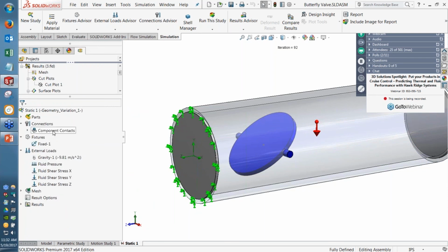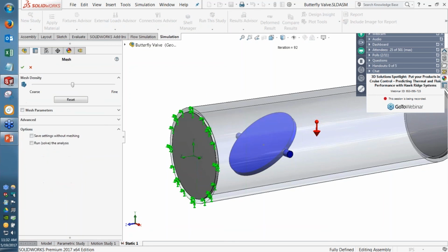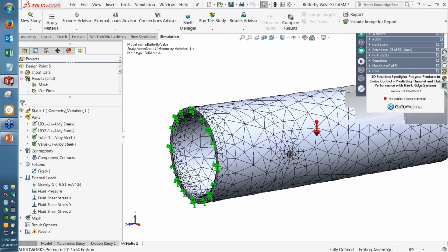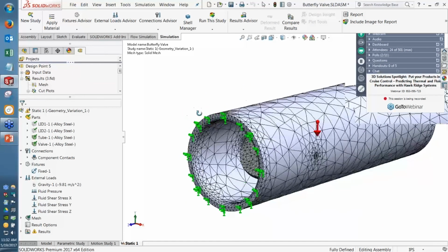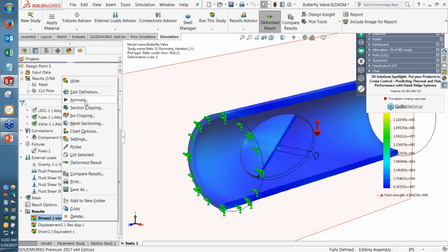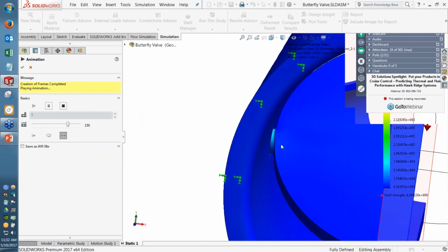It looks like it might deform very slightly at the edges, and maybe there's a little bit of sag in the tube. Of course, all of that would depend on the flow conditions and how much pressure was in my first analysis. With this kind of process, it's usually very practical to evaluate a product in a lot of different scenarios and try different design changes, and then once you have decided the flow conditions you want to assume, those loads can be sent to a stress analysis as well. That's commonly used for things like wind loading or thermal expansion problems.